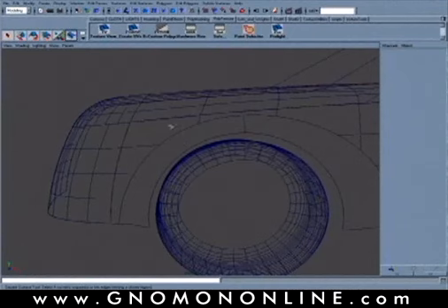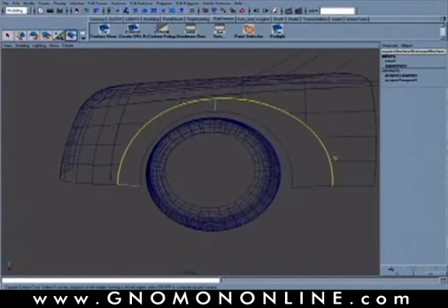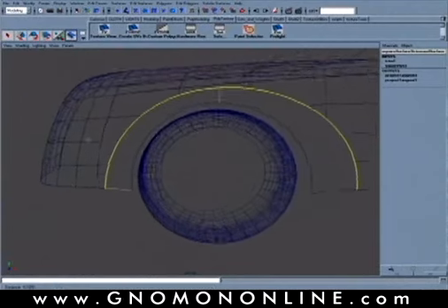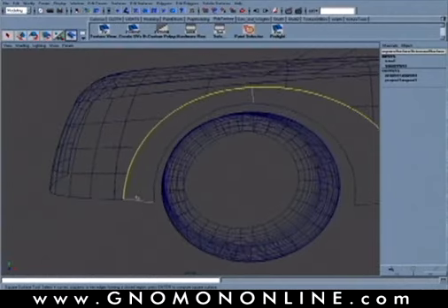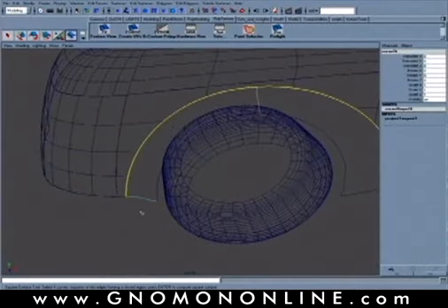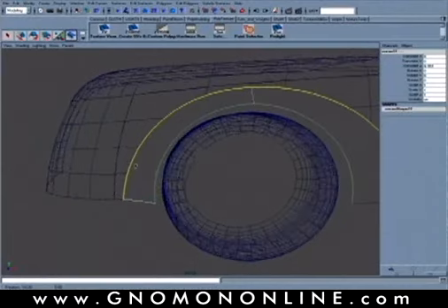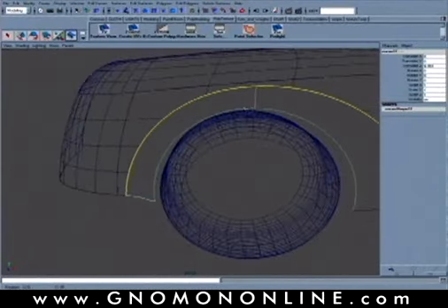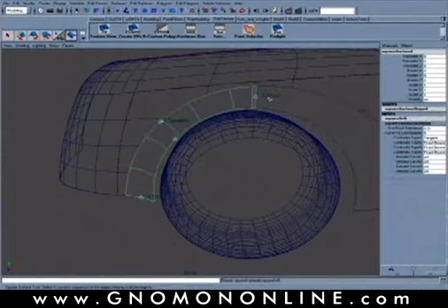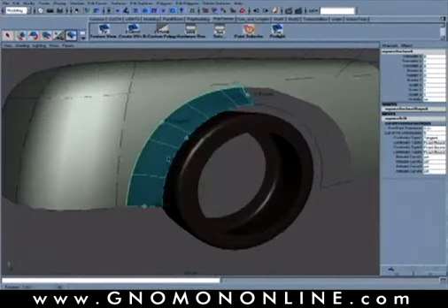First thing I'll do is just drag select or marquee select right over that trim curve. Okay, notice that it will select the entire trim curve because we trimmed this all from one curve here. And then I'm going to select one of my project tangent curves that's feeding into that boundary surface. Okay, that'll be number 2. The third one I'll select is that really the wheel arch or the wheel opening. And then the fourth one we can pick is that center line section. Okay, now this will create then our tangent surface.